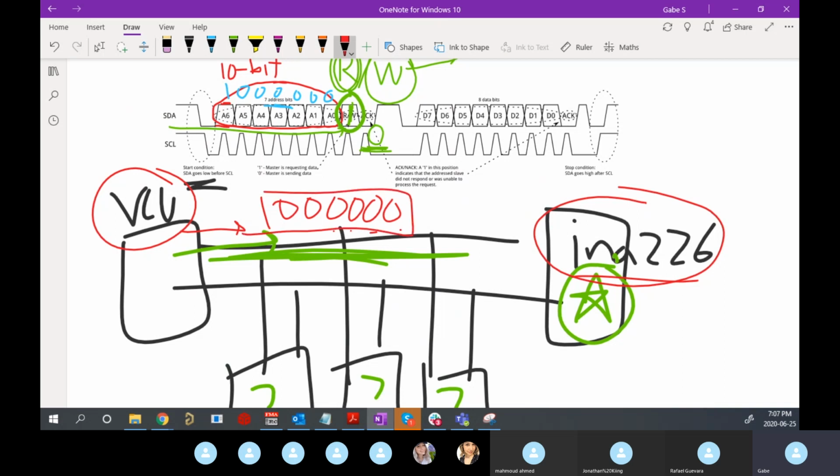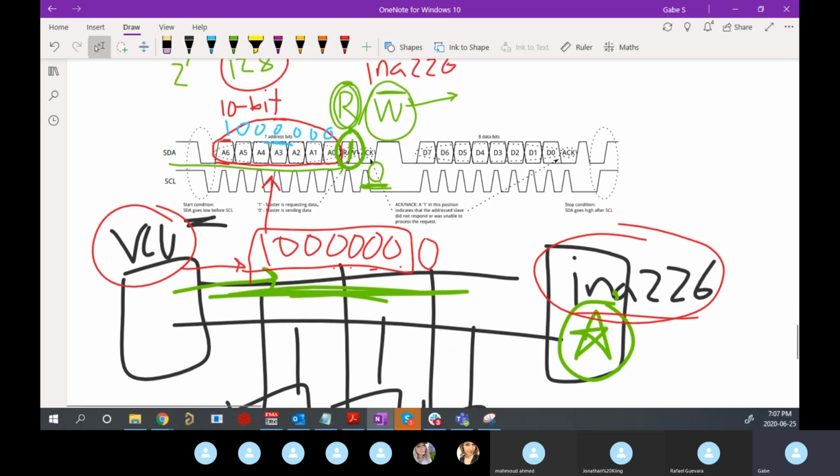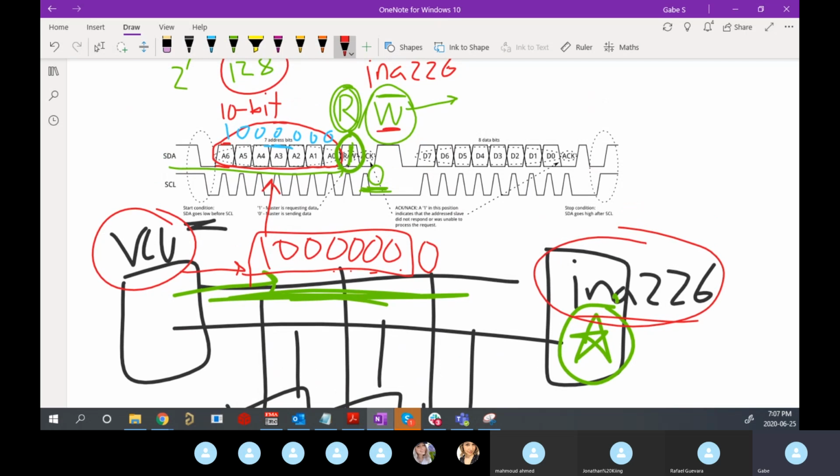So this is the address part from up here. The next thing I would say is I'd put a 1 for my master. Sorry, I want to write to you, right? Is that what I said? I want to write to you. So I would put a 0. Right? We said the write is active when the master sends a 0. It's active low.